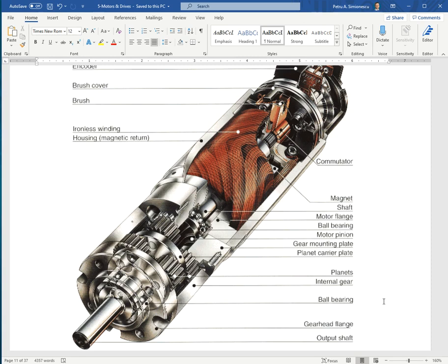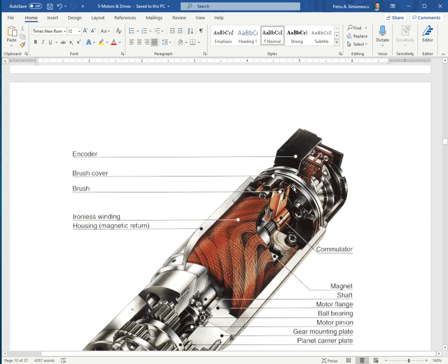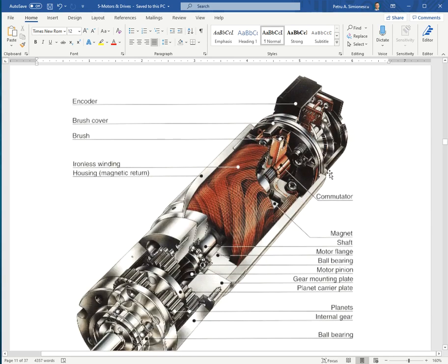There are servo motors with gears that accompany each of the three degrees of freedom. Opposite to the X-axis crank, there is a motor. There's one in series with the Y crank, and there's also one to move the column up and down.